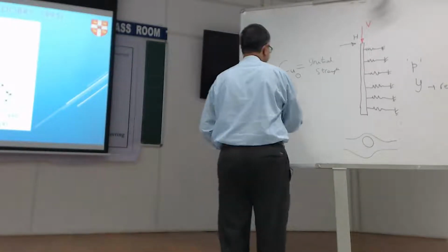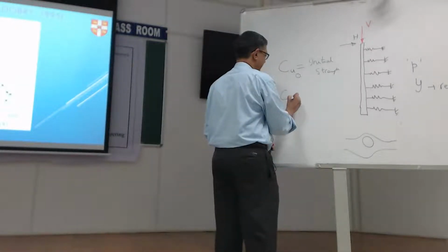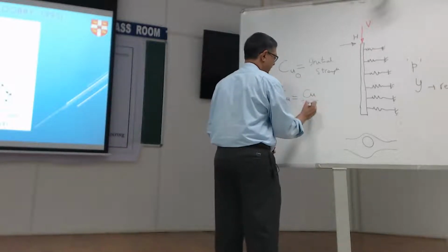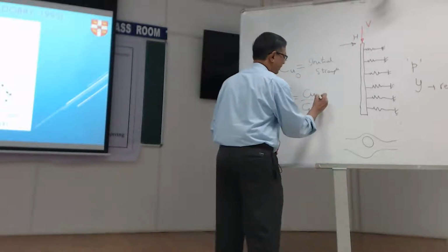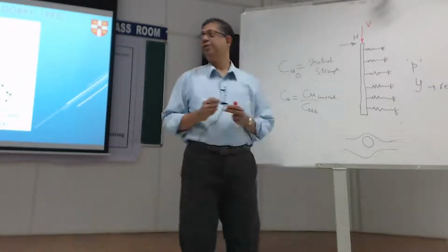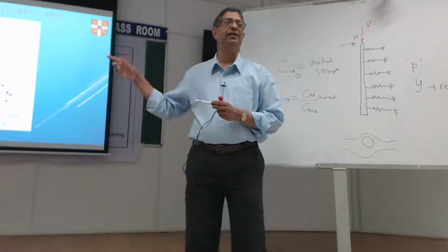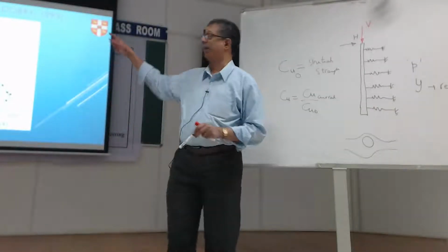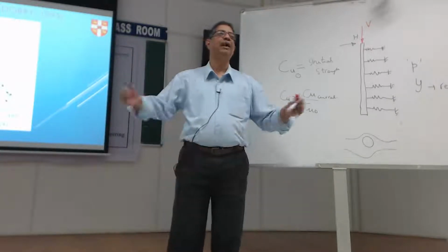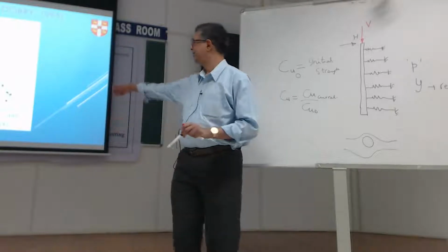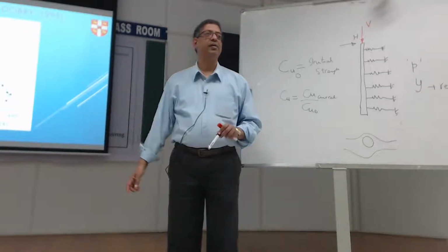Then what they're plotting there is the current Cu over Cu as a ratio. So before any pore pressure is generated, obviously these two will be the same. Therefore, it must be 1. And when it's fully liquefied, this becomes 0, so you should come down to 0.